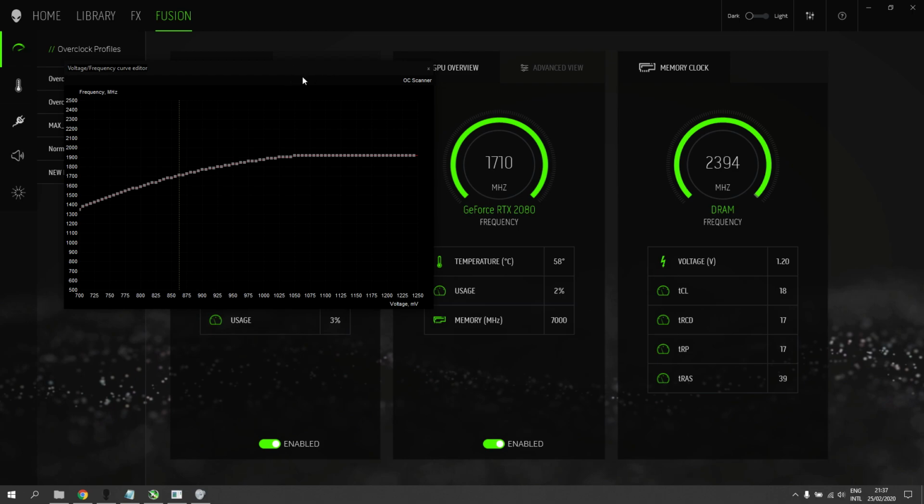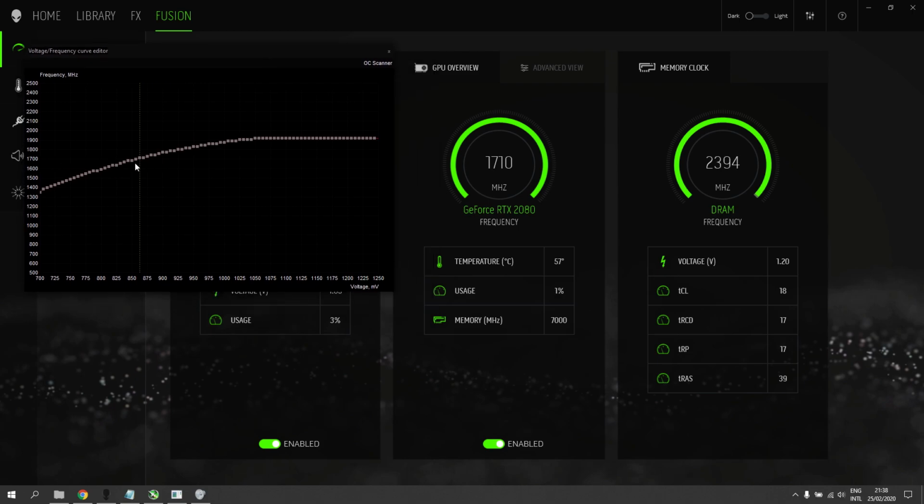So if you remember, this is just finding what is the maximum voltage that we can supply to the card at what boost clock, based on the reference design, that will make the card not overheat, right? So currently we just find, oh, at 0.862 is the voltage that we need to supply the card, and the card will not hit the 75-76 thermal limit that we imposed, while maintaining very close to the reference design boost clock, right? So we found the node.